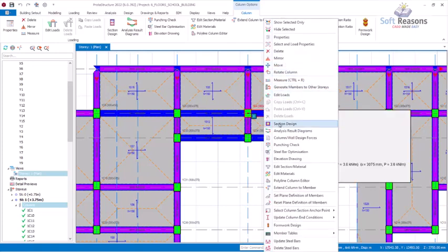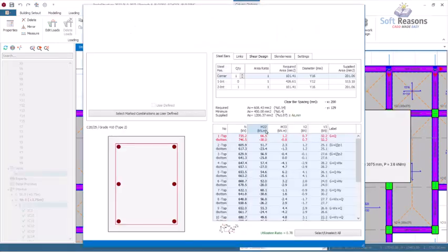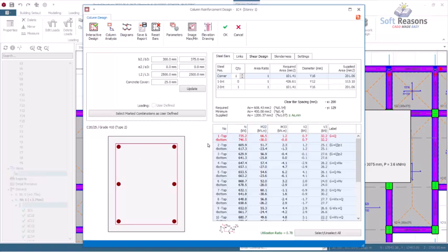I will click on the sections design. In this section design, I have talked about many of these things. So let's get to the B3 sections, and we have to change these sections to 225 by 225, which is 9 inches. 9 inches is just like the width of the concrete blocks we use in this part of the world.